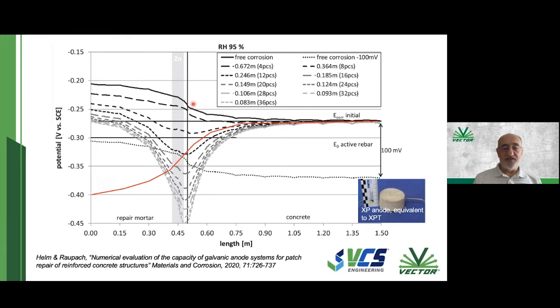And that's why eventually we get corrosion on the outside of the patch. This is the theory about incipient anode formation, or the ring effect. And what we are trying to avoid is that ring effect. Therefore, we put anodes inside the patch. This is now the anode. And these lines show increasing numbers of anodes, or reducing spacing of anodes. So at 670 millimeter spacings, they've done something, but not very successful, really. That's still pulling the potential outside in an upward direction, and it therefore won't work.